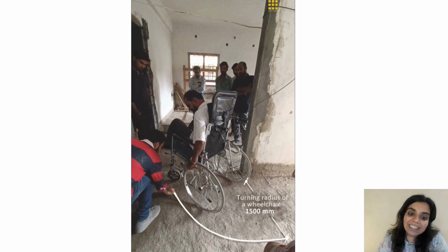One of the very interesting things that happened with us on site is that, as I mentioned before, the door widths are very important. The clear width is not considered excluding the frame. It's considered including the frame. So when we told the carpenter, you've got to remove all these doors and make a clear width of 3 feet, I told him, make one, show me how it is, and then I'll come back to you.